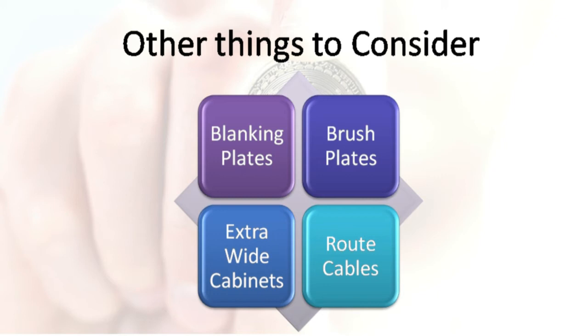The last two, the extra wide cabinets and the routing or rerouting of cables, are basically the same thing, in which the main objective is to not impede airflow and to maximize the cooling air architecture that you will be using.